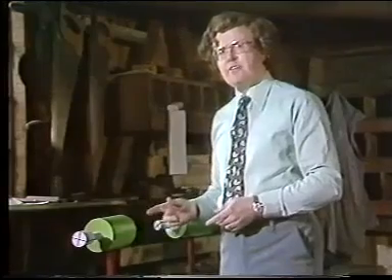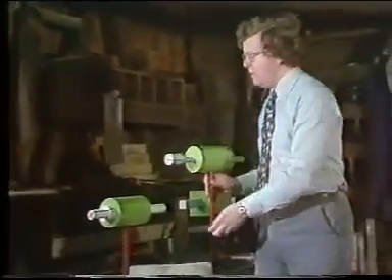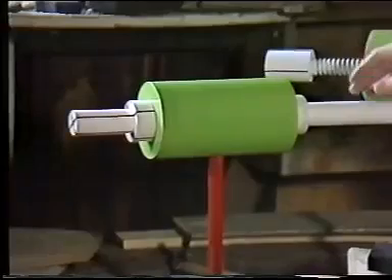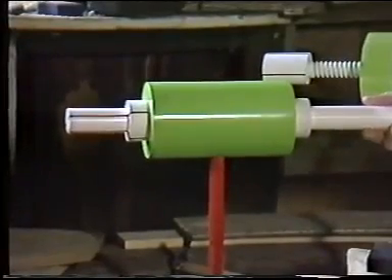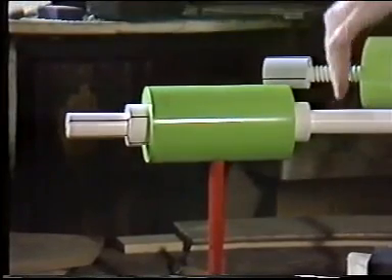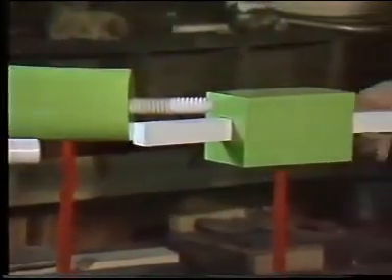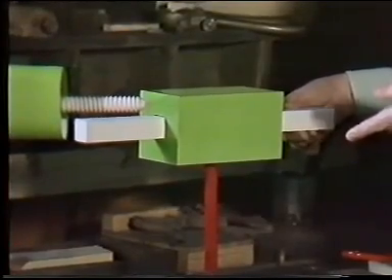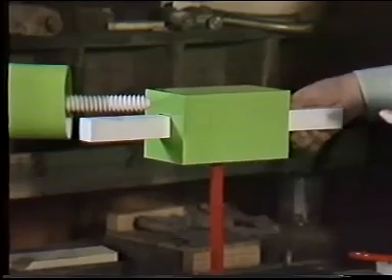And in fact, the screw pair is an interesting one because the other two can both be thought of as a special case of a screw pair. The revolute pair, I can turn it as much as I want, but I get no translation. And so it's like a screw pair, but with 0 pitch, with vertical threads. And on the prismatic pair, I can get as much translation as I want without any turning at all. And so it's like a screw pair, but with horizontal threads, that is, with infinite pitch.